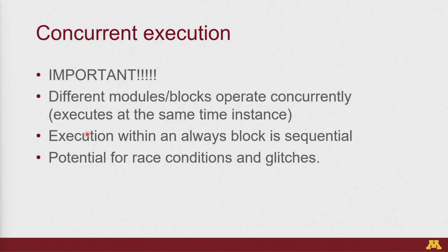Which is literally the definition of hardware. The only exception is that when you have these statements called always blocks, which we will go over in more detail later, anything within an always block is sequential, but different always blocks are again concurrent, right?